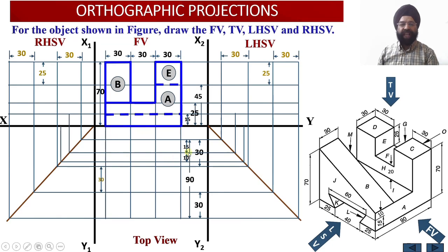We are going to transfer these locations onto the side view, and please check this out. This is a point. I told you that the bottom point is located on the base. So this bottom point will be at a distance of 25 millimeter from the rear face or the rear end of the solid over here. Once I project it onto the side view, I am not going to extend it to the top because this point will be lying on the bottom.